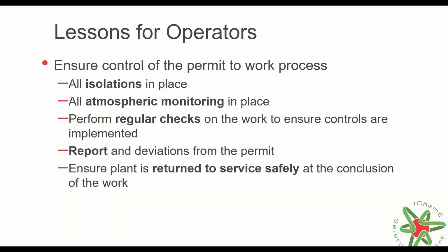From the operator's perspective, so these are the people at the front line working alongside the tradespeople that are doing usually hot work activities. The operators need to ensure that the permit to work process is in place and that they're in control of what's going on. So all isolations are in place.